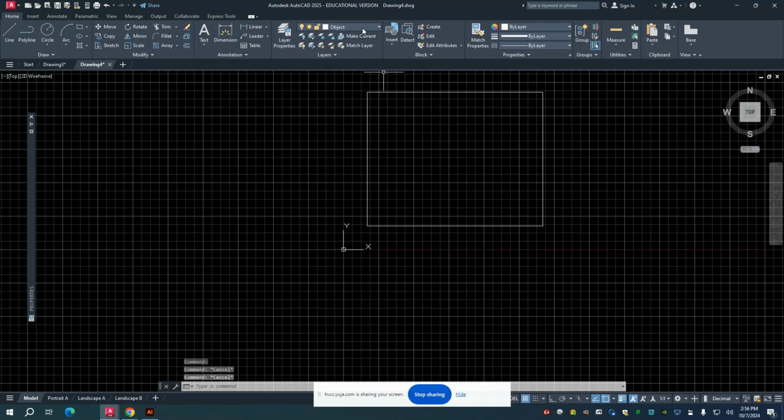And once I did that, I'm going to go back and make sure that whatever I draw in the future will be on the zero layer. And let's draw an ellipse. I'm just going to take the ellipse tool, and I'm going to hover over the midpoint of the bottom, and I'm going to drop my mouse down. I see a green tracking line. And just kind of eyeball this really quick. I'm going to left click my center point. I'm going to bring my cursor up a tad and over to the side.